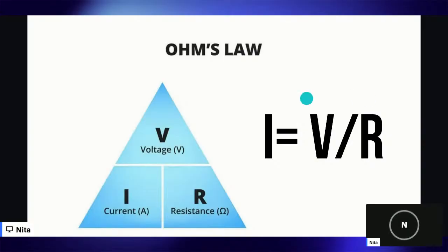Okay, why? Which one of these factors would influence that? Not enough resistance. The resistance of the wire. Well, too much resistance, because if the wire is too small and you have normal voltage, it can overheat because remember, the resistance is going to convert that energy into heat. So that's why wire size and breaker sizing are so important.